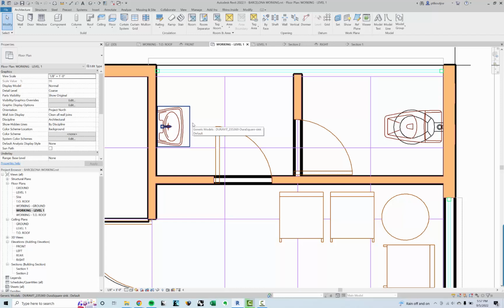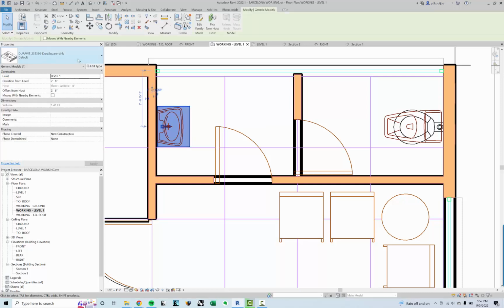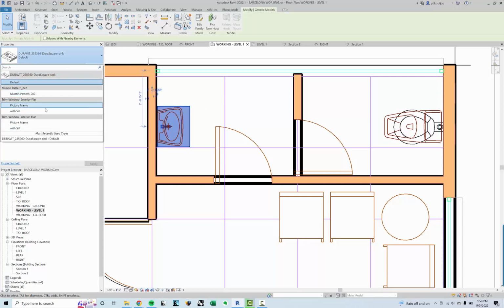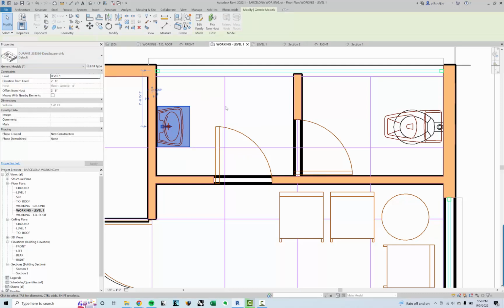There's lots of good things on there. The one thing to note is that once the family is in the model, it's there forever. It doesn't link back to the server or anything like that. So while you do probably want to file things away nicely, it's not like InDesign where if the link moves, it'll break. Once the family is in here, it's in here forever. And now that model exists within my components here. All right.